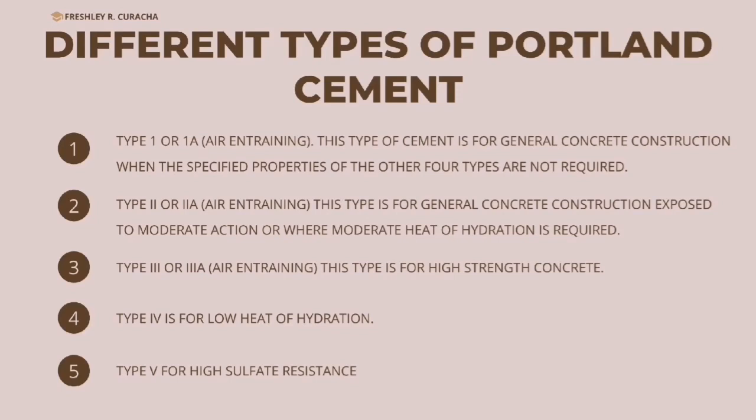It is ideal for applications which require quick setting so that structures can become operational faster and where formwork needs to be removed and reused. It is also ideal for cold areas where the quick curing of concrete prevents damage due to frost.